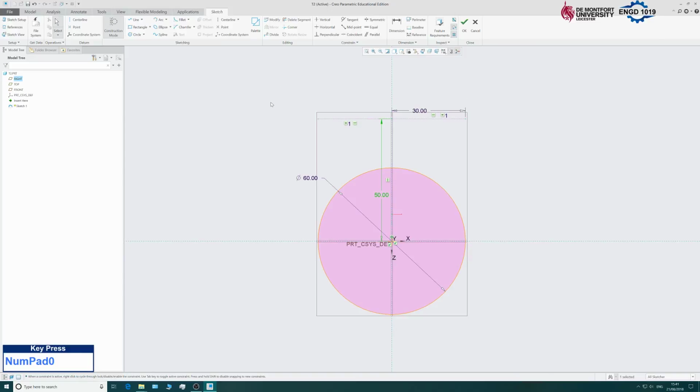Okay. So if I come out of construction mode now, I'm going to draw the outline for the circles around here. So use the circle tool. We can see that the outline, they have a radius of 20, so that means that their diameter is 40. So if I draw two circles, I'm going to make them equal length, so you can see snap to equal size, and then press the middle mouse button. So just change these to 40.